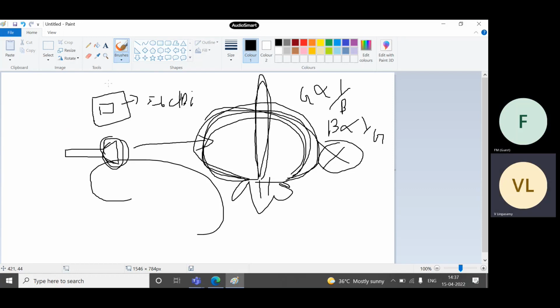So now, when you want to move on to high gain antennas, what are the options? One is the parabolic reflector, the traditional way. For more than 70 or 80 years, they have been using this parabolic reflector antenna. What it does is, you have a feed horn. It can be a feed horn or dipole, anything is fine. This feed horn will illuminate the wave something like this.